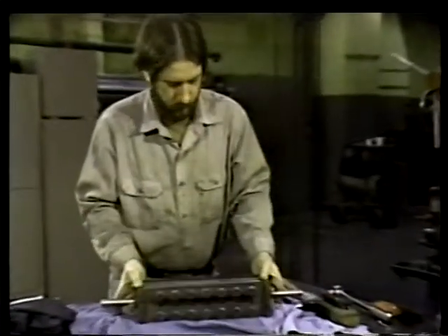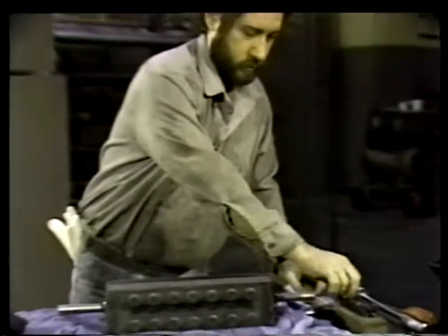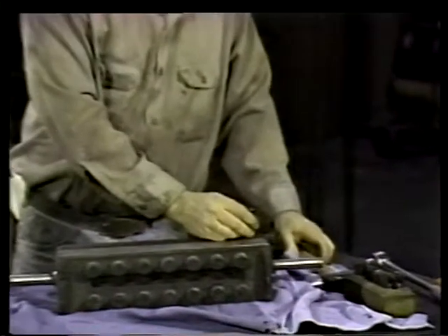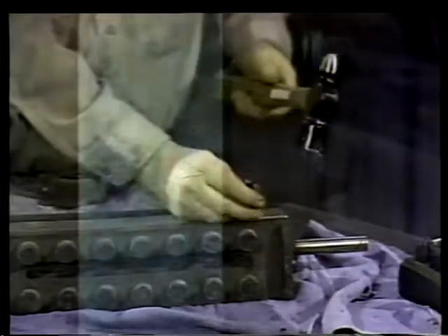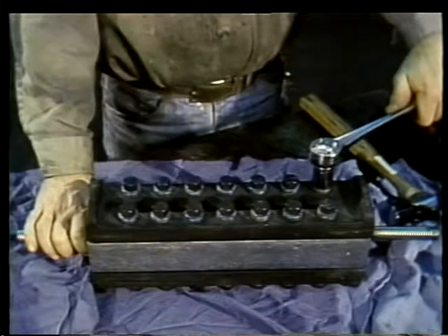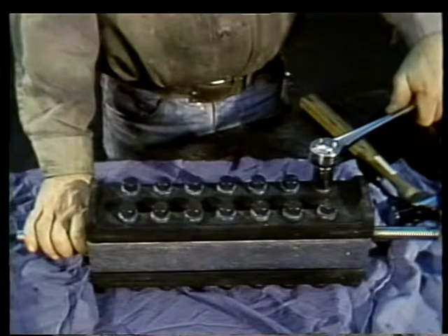The cover plates and gauge body should be match marked so that they can be put back in their original position. Match marks can also be called witness marks. Once the gauge is marked, remove the cover plates from the gauge. Starting at the ends of the cover plates, remove the bolts and washers.